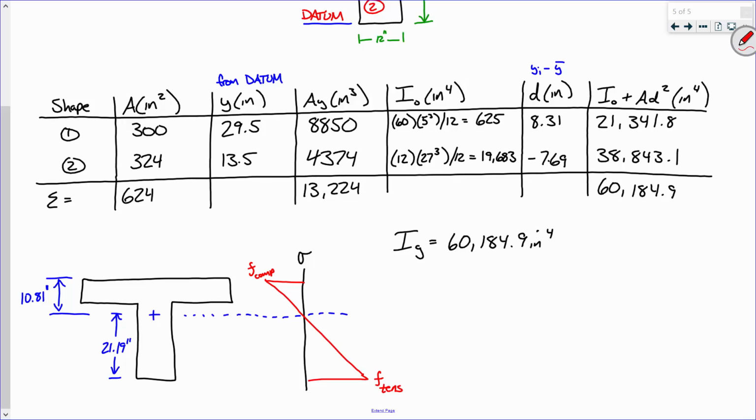Okay. All right. And everybody okay with this? So real quick, in terms of notation, I'm going to call this distance y sub c, just like last time when we did the rectangular beam, we called this y sub t. So from the centroid to that extreme outermost fiber, we're calling that y sub t and calling this y sub c. Just so you're aware of the notation that I use later on. I'll give you all a second to copy this down while you're writing. Doesn't the y sub t really mean like the distance from the centroid to the tensile member?